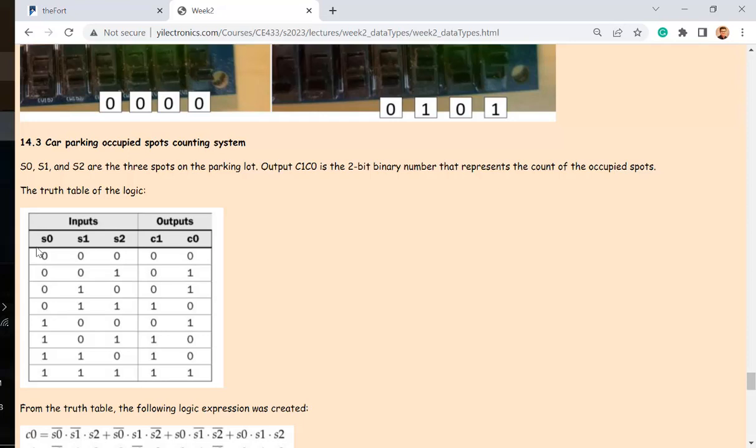So this is what the circuit is going to do, right? Just processing and outputting how many spots are still available. So these 0s and 1s can be the output from the sensor. If a spot is being taken, then the receiver has a different signal and is outputting a different signal to the microcontroller. We don't even have a microcontroller here. It's just very simple conventional logic, right? And it can still do the job. Not ideal, but it can still do it.